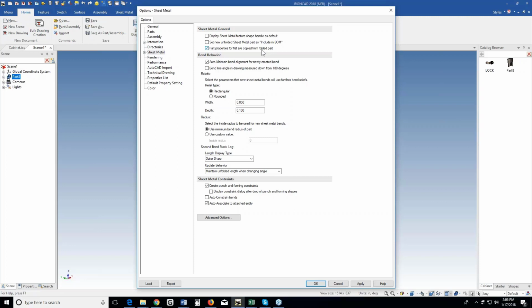So when we create a sheet metal part that has press brakes in it and populate the data, then go to unfold that part, it will automatically transfer that information to the folded part. Another option that I like to use is for bends: we have controls for what the bend dimension is measured from: flange, tangent, inner sharp, outer sharp. I typically design using outside dimensions, so I like to use the outer sharp.